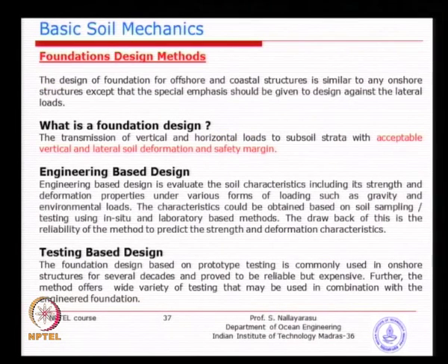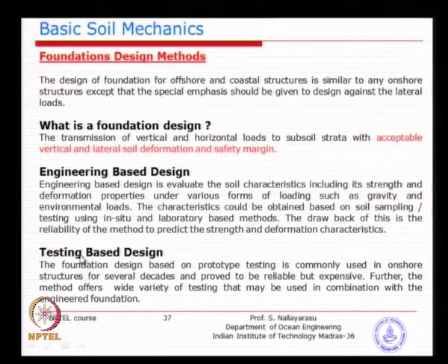After that, you do the testing and compare the capacity. You have done your calculations for 10 meters of depth of penetration or 20 meters of depth of penetration. Some capacity you have calculated based on what you have understood from the laboratory testing characteristics, plus your understanding of the soil and applying mechanics principles of load transfer, either by shear or by compression. You calculated a capacity based on theoretical methods using the results from laboratory and field testing, and now you have constructed that foundation, done the testing, and you compare these two capacities.